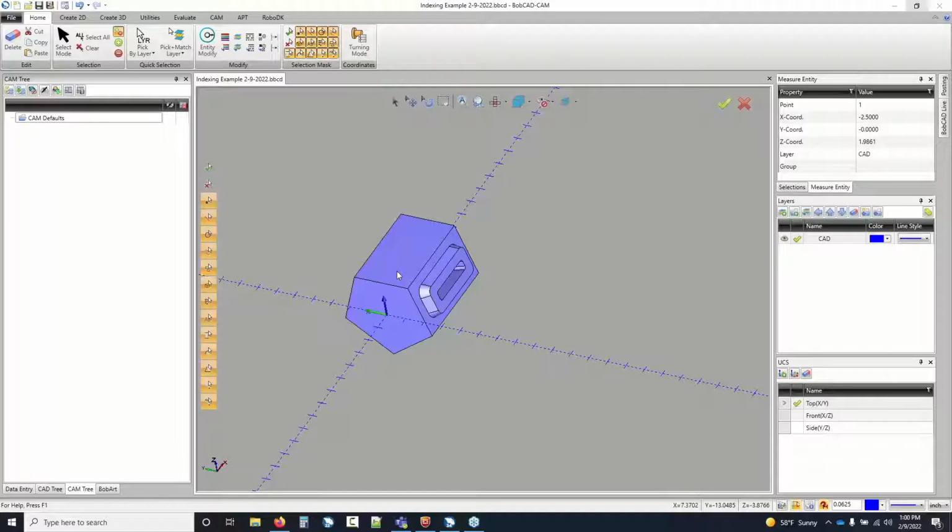So today we're looking at the 4-axis standard from inside of BobCAD-CAM. Now, before you get into 4-axis standard, the best thing you could do is understand 2-axis and 3-axis, because really all the 4-axis toolpaths that you create are pretty much just a version of a 2-axis or 3-axis. Now, that's not always true, because there's things like the 4-axis rotary toolpath. But most of the time when I work with guys doing 4-axis, there's two main things we're doing. It's indexing and wrapping.